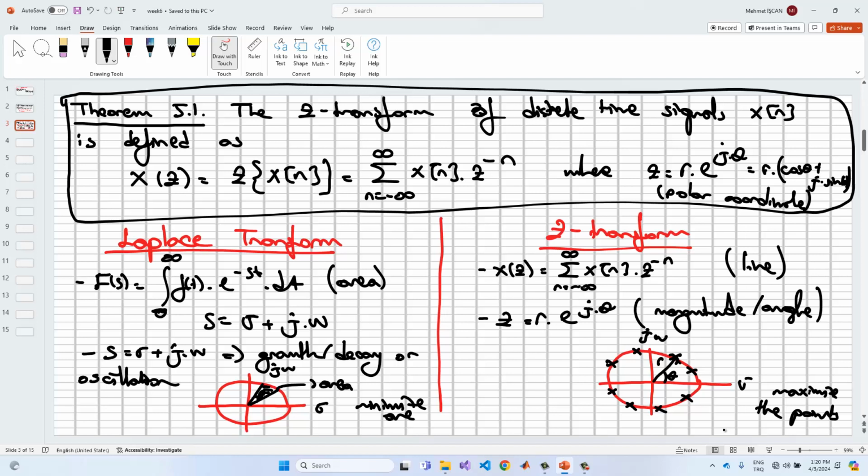It's a disadvantage. But if we want to use the microcontroller or the microprocessor or the computer structure to evaluate your signal or the system, we should always utilize the Z transform, because microcontrollers or computers run based on the sampling rate. For example, a 4 gigahertz processor or a 5 gigahertz processor. Everything is discrete in computer structure or in electric and electronic engineering. Okay? You need to understand that.